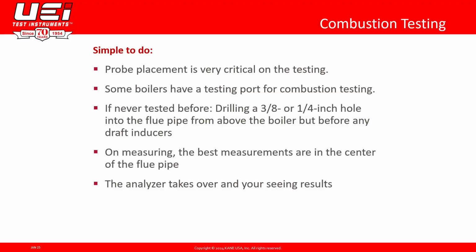So once we've set up the gas, now we can move on to our actual combustion testing. If you are working on equipment that has never had combustion testing before, it is possible that you might have to drill a hole into the flue. If you're doing a new install, there are really cool combustion tees that you can buy and put in line, so you can set future you up for your combustion testing. But once we've gotten that in place, and we only have to drill about a 3/8 of an inch hole, we're pretty much ready to do our combustion testing.